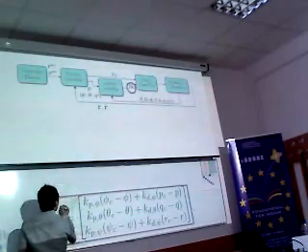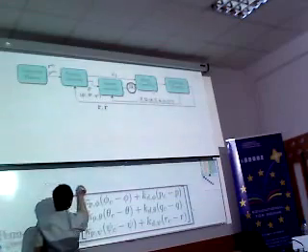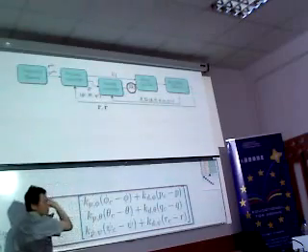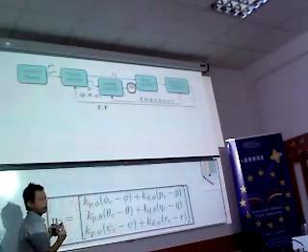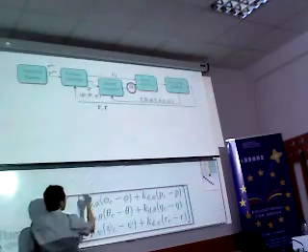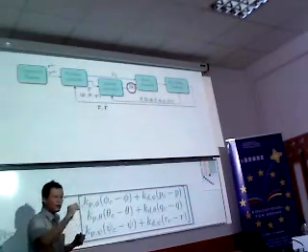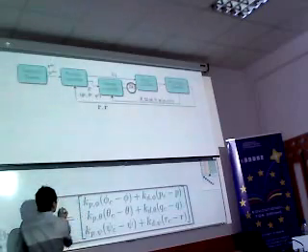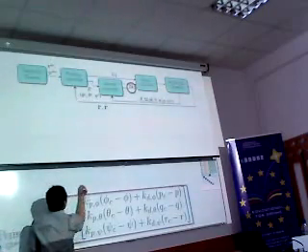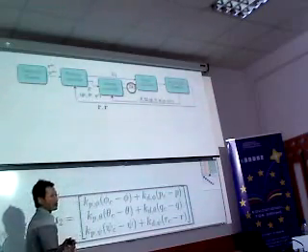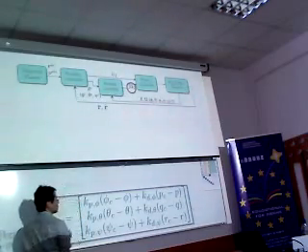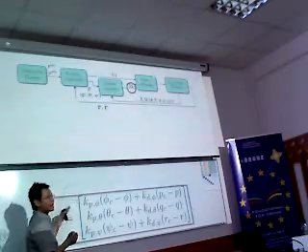The response of the system will be better because the time that the system takes to reach the stable value is less, right? And it has no overshoot, so the system does not oscillate like this one, and it reaches our stable equilibrium, right? So you have to choose the right coefficients KP and KD.